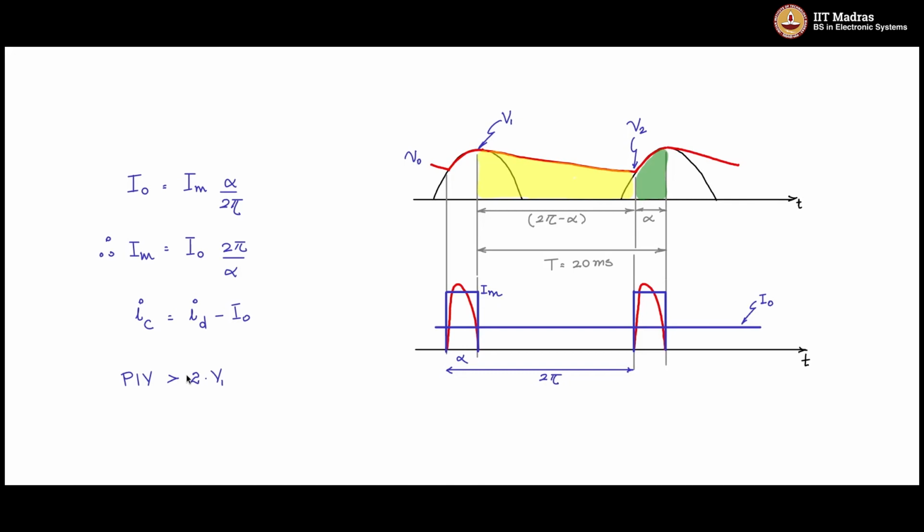So let us say you have a current of 7.5 amps, then you choose a device of at least 10 amps. So if I am having a device having a current rating of 10 amps, then as a thumb rule, do not allow more than 75% of its rating, which is 7.5 amps, to flow through it. This is to give a buffer safety margin for all the devices that you select, to take care of some degree of uncertainties and unmodeled dynamics which we are not aware of.